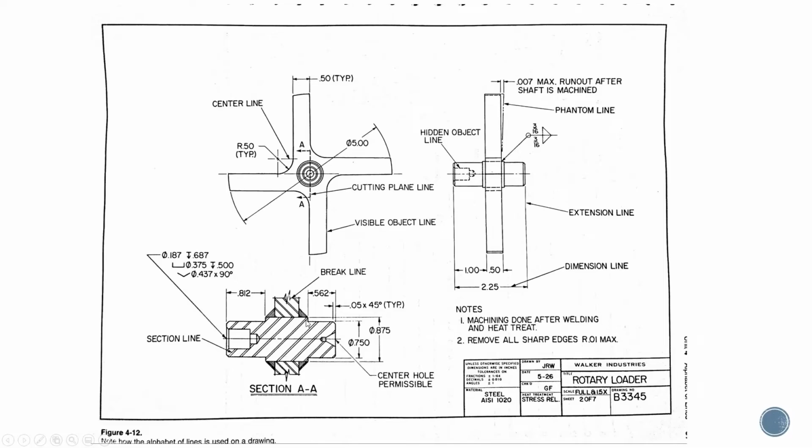And you can actually see the welding indicators here. We haven't talked about this yet, but these are indicators for that weld, these hash marks in here at an angle. And up here you have another welding designation. This is a leader line coming in, showing welding information, so the weld bead that you're looking for in that case.